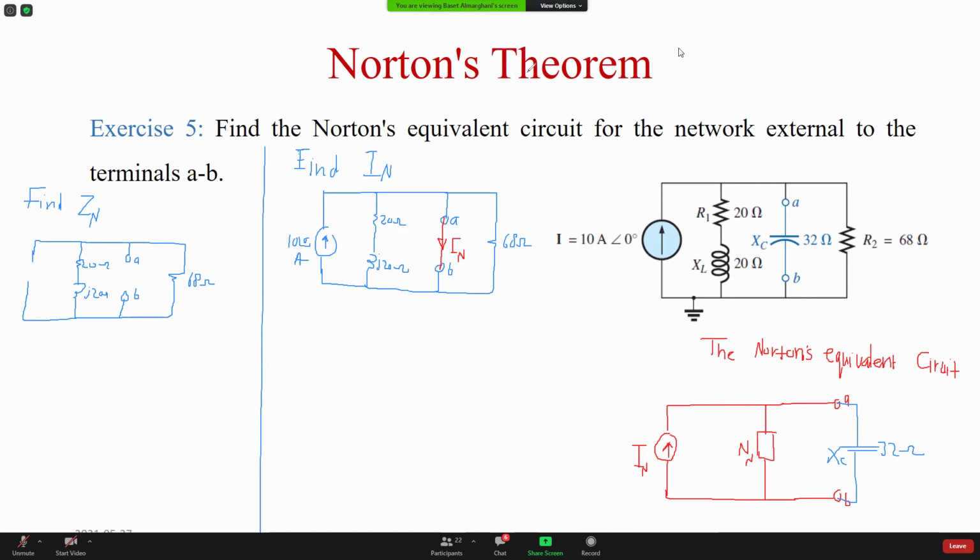Now the analysis, I'm gonna simplify this one. The open circuit branch has nothing there, so an open circuit is not gonna affect the branch. An open circuit branch is not gonna affect my total impedance, because its impedance is infinity. So I can draw it.